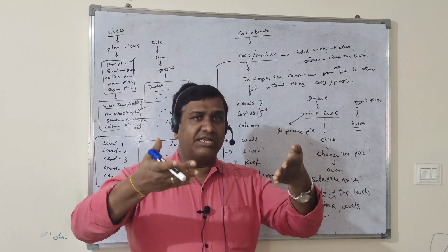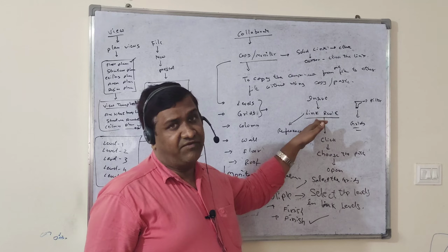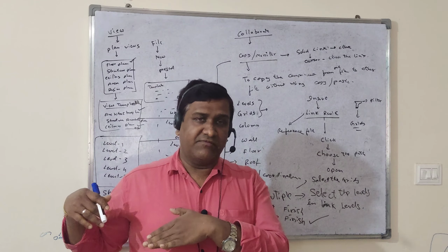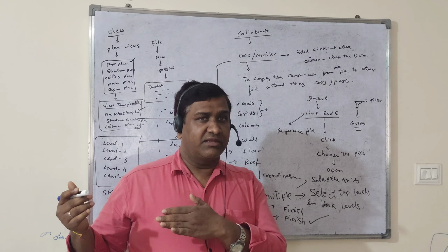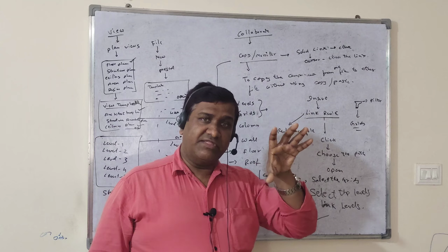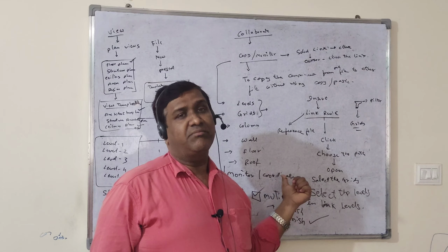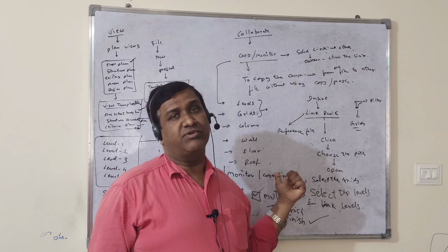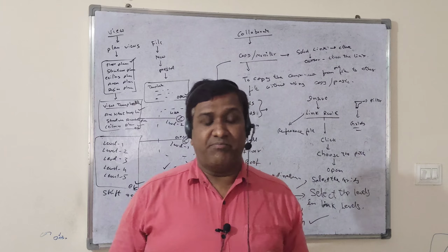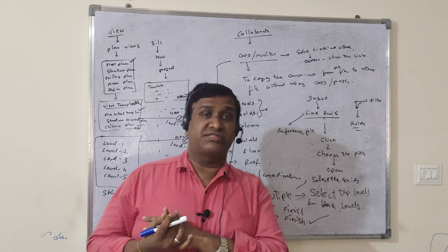So again, you have to take that tender drawing as a reference with the help of Link Revit file. You have to link it in your project, in your template, whichever template you are using for the shop drawing. Just link it, and whatever levels and grids are in that tender or design drawing, you have to make them Copy Monitor. This is the way we have to do it.